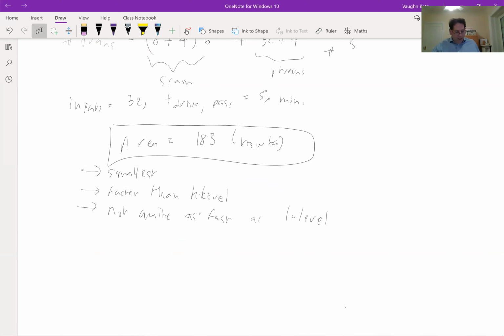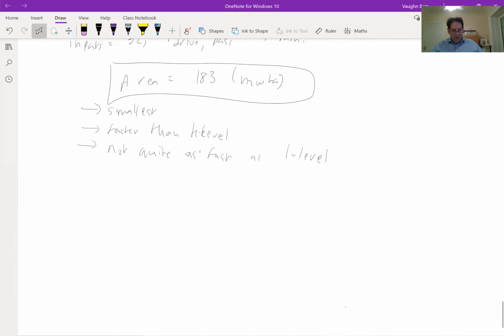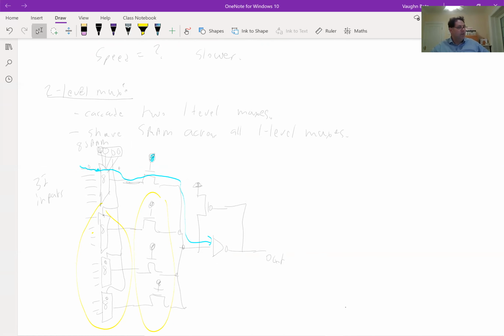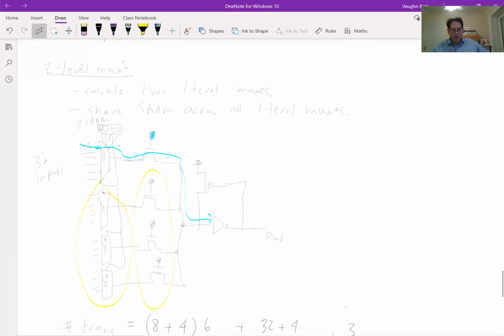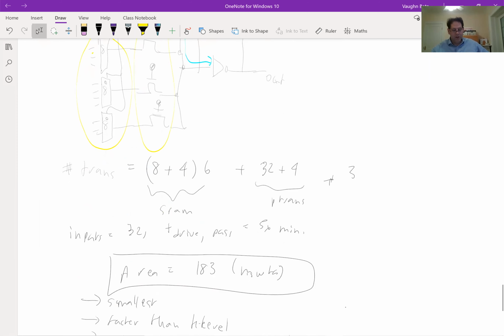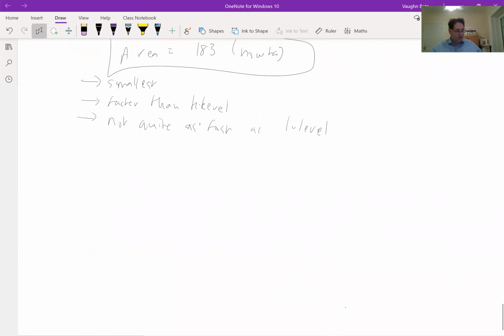choice. And it's actually the dominant choice in most FPGAs. So FPGAs actually do exactly what Kimia mentioned, of exploring all the options of how many levels you're going to do. Usually the best choice for small muxes, 1 level is usually the best, but small means maybe 4 to 1 or so. And once you get beyond that, 2 levels is usually the best, but not always, but it's the most dominant one.